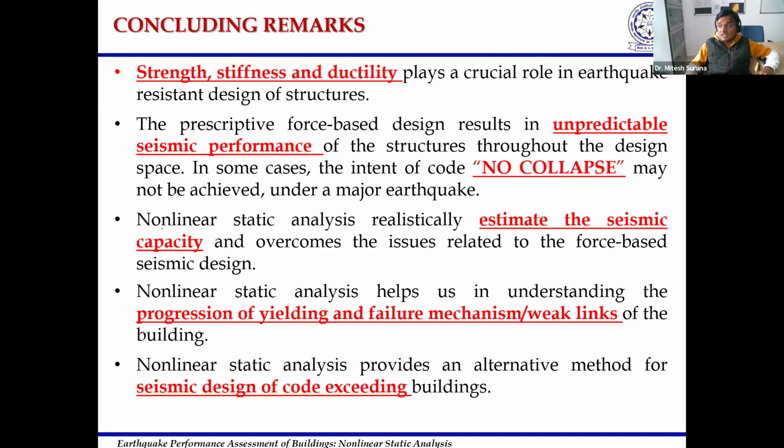And if we want to change the structural failure mode, that can also be done by modifying the structural design. And nonlinear static analysis also provides an alternative method for seismic design of code exceeding buildings. So for buildings where the code provisions are not applicable, in that case, we can conduct actual nonlinear analysis and we can see what will be the realistic values of different parameters that can be used for their structural design, that can be verified through this nonlinear static analysis.